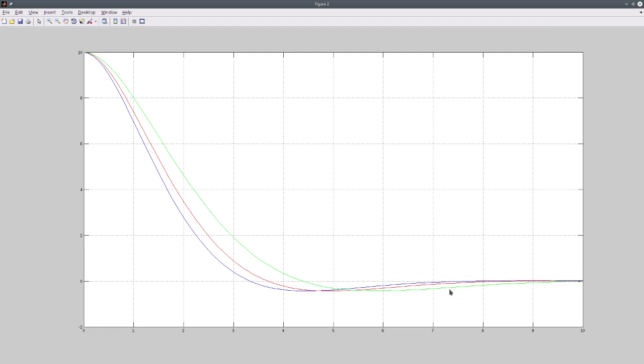Okay, so that's our example, and please try to play around yourself with LQR and playing around with Q and R and different components of the weighting matrix, so that you can actually put an emphasis on different components of the state vector, as well as, let me note that LQR is primarily used in order to design systems which actually have constraints on the input.